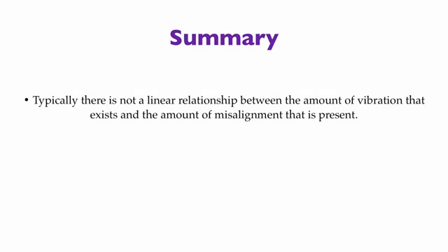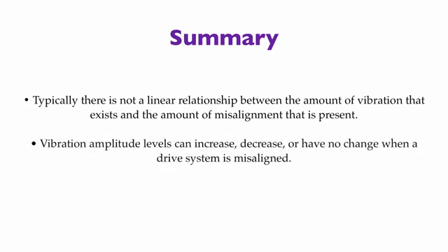As we've seen in the intentional misalignment experiments, there does not seem to be a linear relationship between the amount of misalignment and the amount of vibration. If you double the misalignment, the vibration may not necessarily double and in fact may decrease rather than increase.